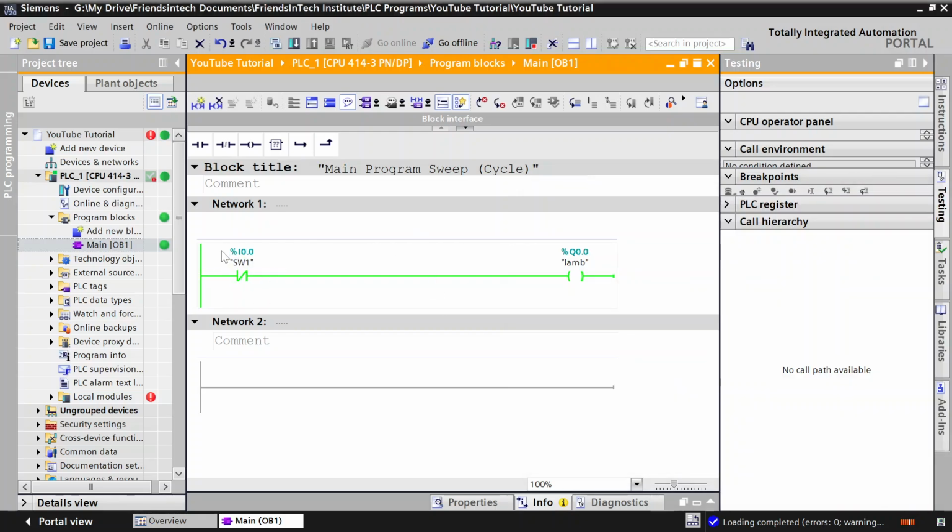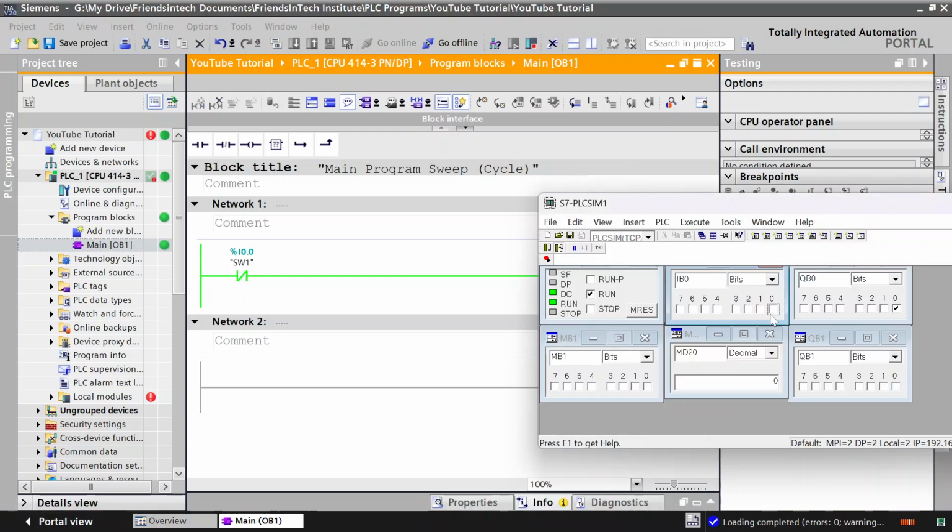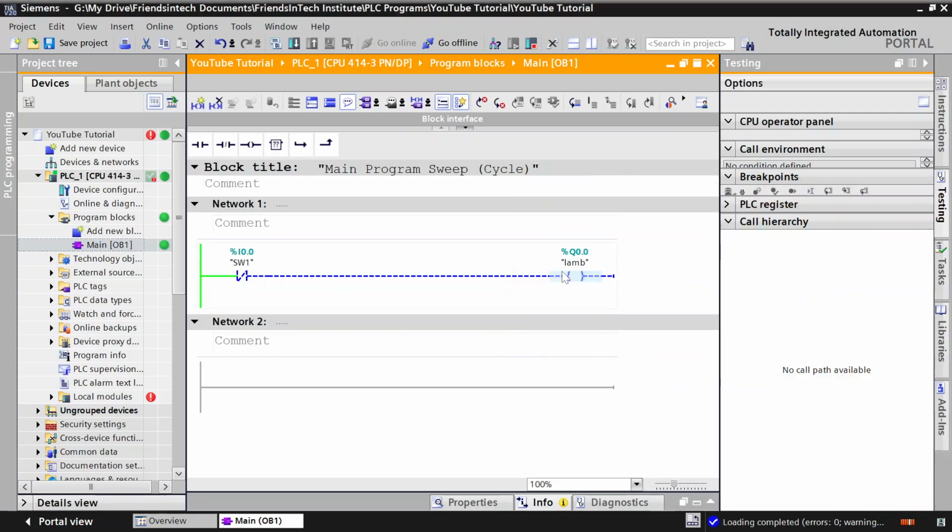So you see, with normally closed, it is a short circuit in simple terms. So the power will flow. That switch is normally closed by default. Now, when the sensor detects an object like this here, we can change the state here. So it will change to normally open, therefore breaking the circuit. Those are the two concepts that you really need to know when you want to program using ladder diagram. You need to understand what is normally open, what is normally closed, and what is this coil here.